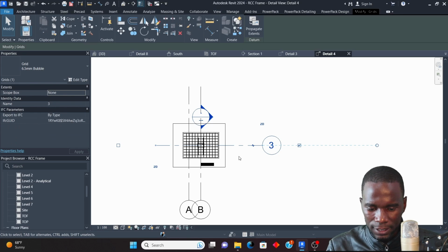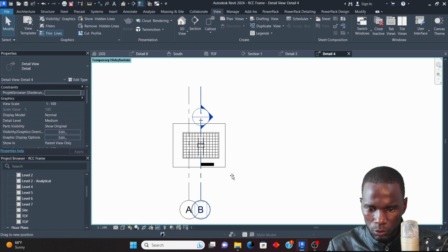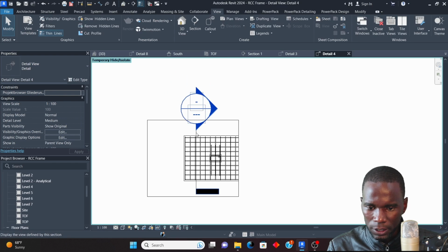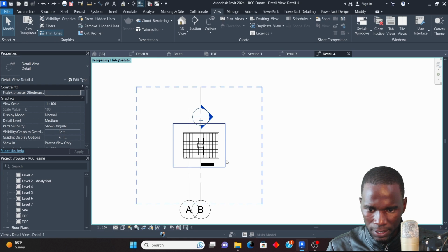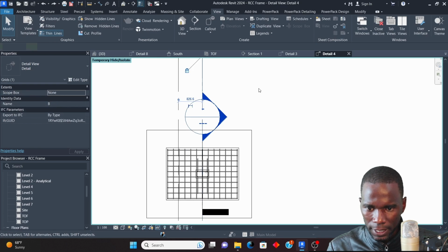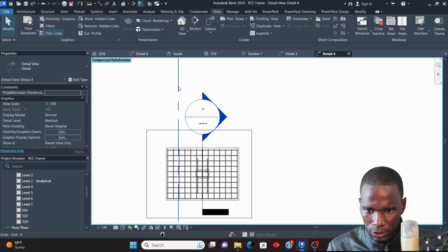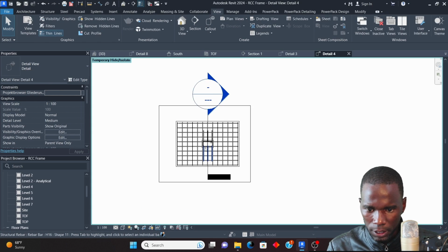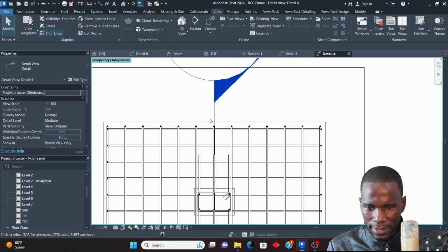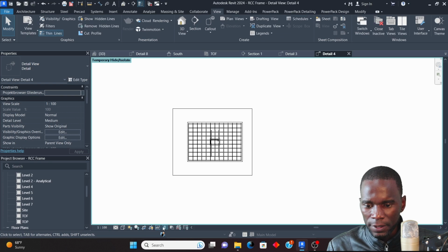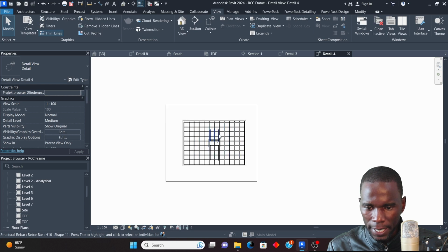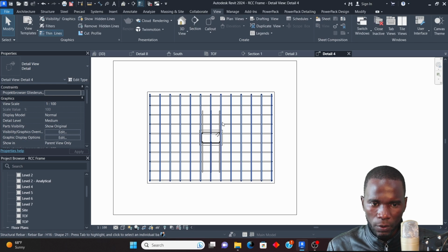Okay, then I can start selecting on that, HH on your keyboard, just to hide what you don't want to see. Or what have I done? Okay, don't crash on me. Okay, HH on my keyboard and just undo so that I see what I've done. Okay, so I'll select on this one, HH, select on that one, HH on your keyboard. We have this one. Okay, I think even the section, I don't need the section, HH on your keyboard. This is a shortcut for hiding. Then once you do that, just click there and apply, hide, isolate. Everything is hidden. All right, this is one detail.